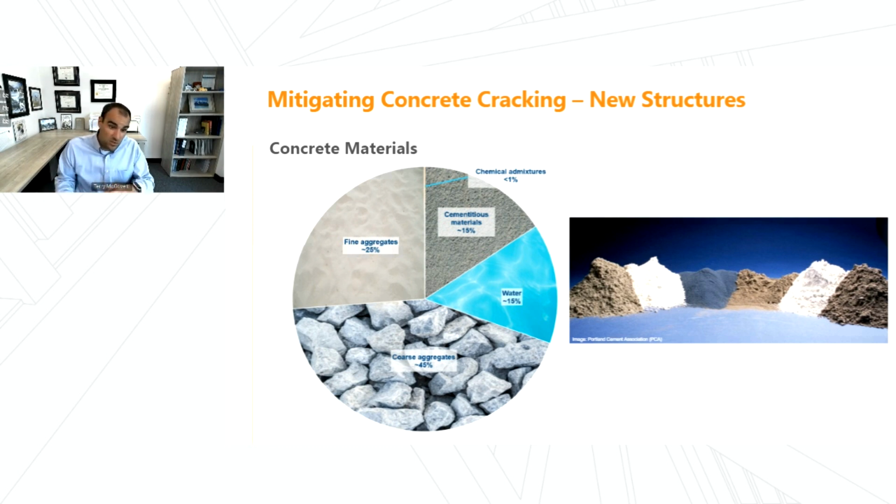We've got some chemical admixtures. We got some fine aggregates, those are our sand that goes in. We got coarse aggregate, the rock that goes into the concrete. And then we have water and cementitious materials. So that's our cements, our natural pozzolans, our supplementary cementitious materials. All the other things that are going in is powder, and that's shown in the figure on the right. Those are the powders going in, and those are the things that are reacting and taking us from that plastic state into our cured hardened state.